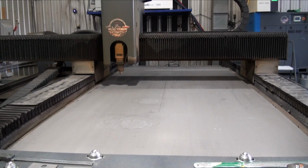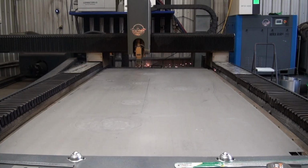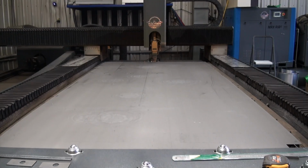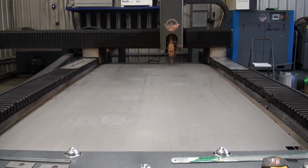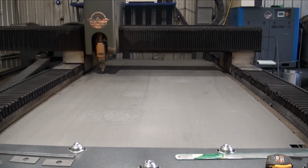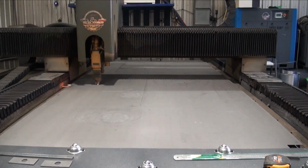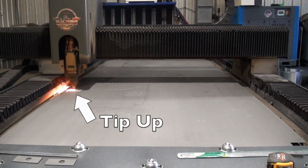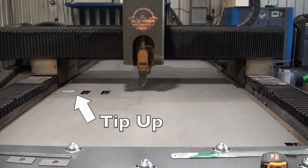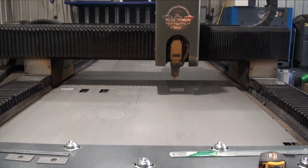We'll do a time lapse to show you how everything cuts. So this 14 gauge sheet, which is .070 inches, took about 4 minutes to process. Now when we programmed it, we didn't utilize smooth micro joints, which would have prevented the part negatives from tipping up. We hit pause on that and knocked those out of the way, so we didn't actually get a tip touch. And that's really important.